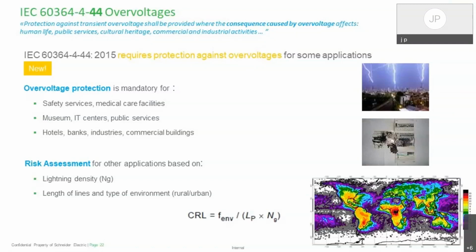It's really what you have to consider that we have more and more electronics in the installation, and therefore they are much more sensitive to overvoltage than the resistive loads we had in the past, and more protection against overvoltage becomes mandatory in the installation. So it's something really important to implement. And then you also have in part 5 the way to implement this overvoltage protection, which is very important, because if you don't install the overvoltage protection correctly, then it's not effective at all.